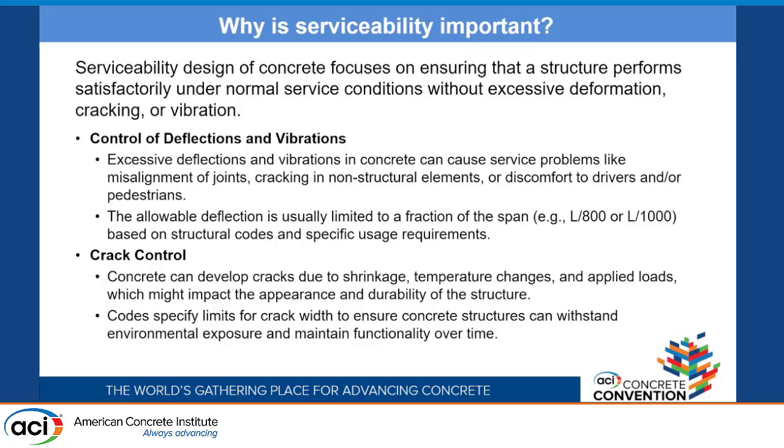When we're designing for the service limit state, we're trying to do two things, right? We're looking at the deflections and vibrations we talked about in the previous presentation, the effect of vibrations, how that makes people uncomfortable. So same thing on our bridges. If you're going across a bouncy bridge and you're driving in a vehicle, that could be discomfort to the driver, or oftentimes we have sidewalks. Then the pedestrians on the bridge would feel discomfort from excessive vibrations.